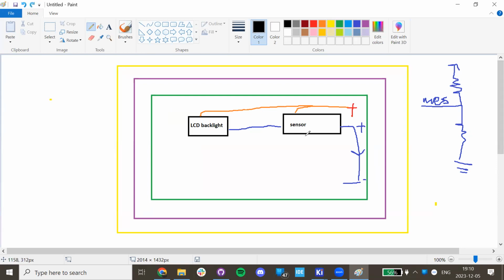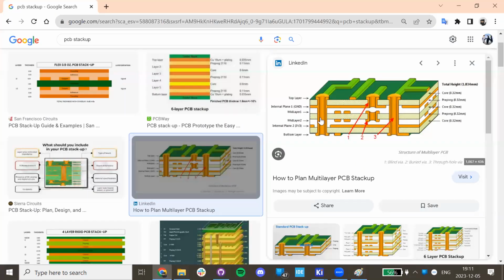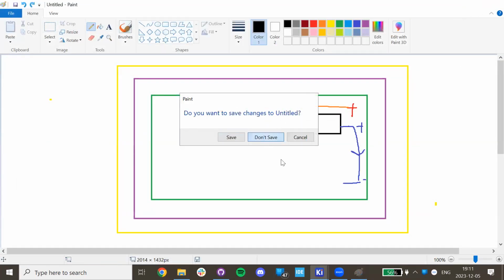And usually we do a ground plane, and it's partly because of that, partly because pretty much everything needs ground. So if you have a ground layer, it makes everything easier. Then the front, we also make ground, and that's also to make the routing easier, but it's not primarily for the current to go through the top plane. You usually want to add a lot of these vias so that your front and your back plane are extremely well connected, and these vias can carry relatively large current compared to the traces. Okay, so now we're going through a small bit of the background.